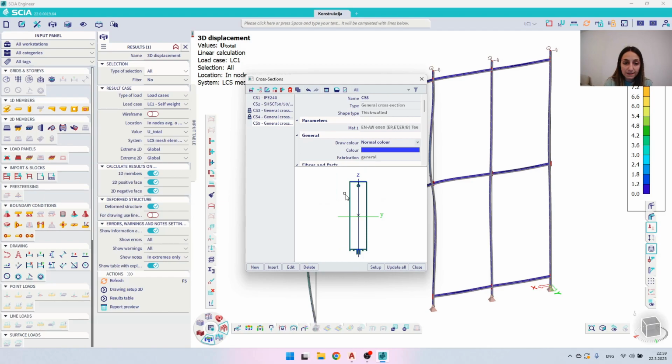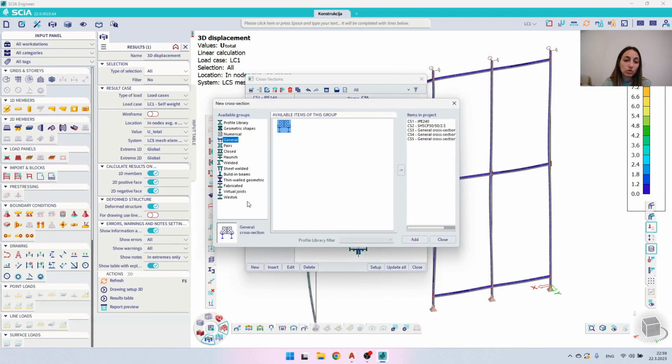and apart from the polygons and their openings, there is another cross-section. There is another type of cross-section that can be imported into the general section editor in SCIA. If I go under new, you can see that I also have the thin wall geometric sections, but the library of the thin wall section, the geometric shapes are somewhat limited. So if you don't see your cross-section in here, don't worry about it. You can simply draw it in AutoCAD and with the general import it in SCIA.